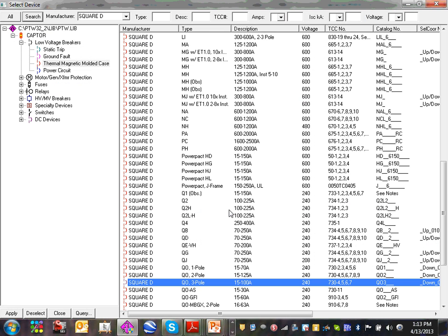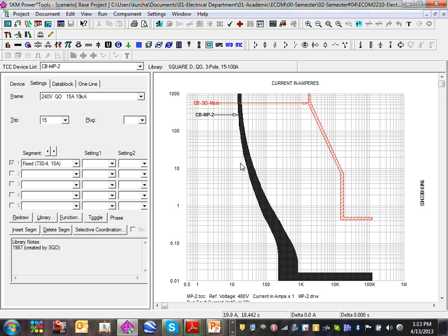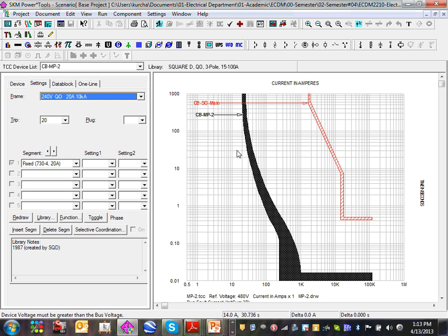A 3-pole QO, right? 15 to 20 amp. This is how it looks, that's the curve. This is your 15 amp that you put on your lighting circuit, QO. 3-phase. Again, you can put single phase, but let's just say 20 amp because it's the most common. Here's a 20 amp. That's how the curve looks. What does that mean, guys? If you exceed the 20 amps here, it will take a while to trip, but it looks like it's rated for, here's 100, 200, 300. If you put close to 300, maybe 150 amp through this circuit breaker, it will trip instantly.